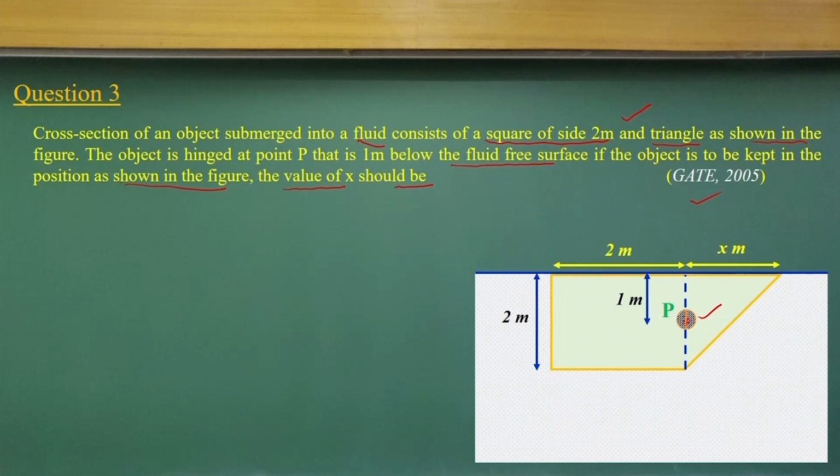These are the hinge locations. But what is the basic concept of this submerged object? There will be a horizontal force acting from this side, and also a horizontal force acting from the other side, but those will cancel out. The same amount of horizontal force acts from each side, FH1 and FH2. If I consider both, they will cancel out. What will be the difference?